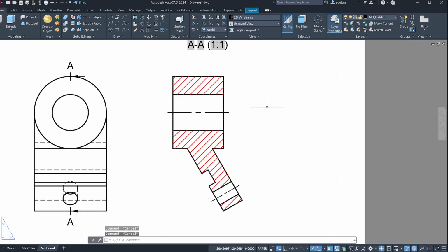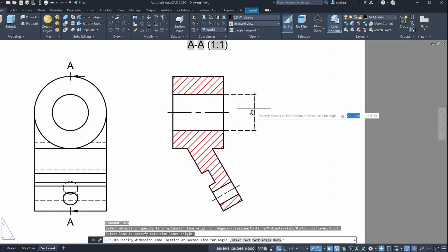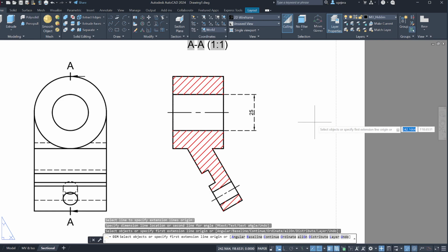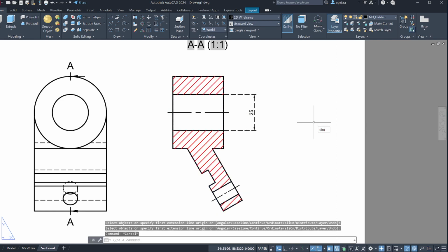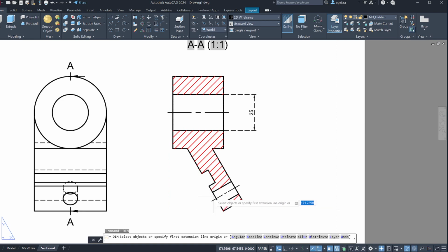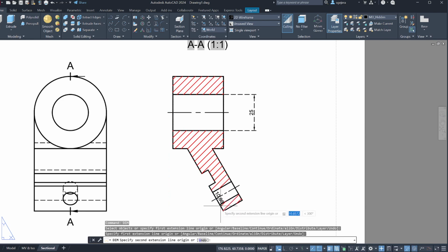Okay, and from here, pwede naman if you want to add dimensions, same as before, no? I think we did this in class. From the layout, you can actually add dimensions now. So dim, you can use the dim command. Like for example, ito, I can place dimensions there. I can do dim. I can place, ito from here to here. So on and so forth.